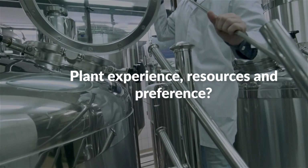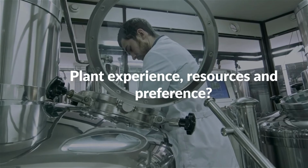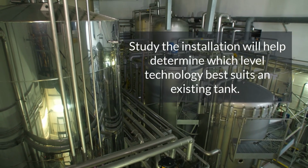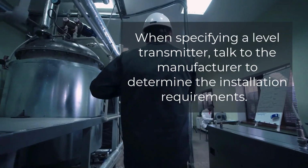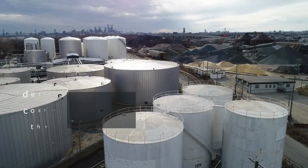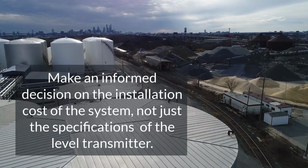Weigh in the plant's ability and inclination to support and service the instrument. No installation will be successful without it. Studying these areas of the installation will help determine which level technology best suits an existing tank. When specifying a level transmitter, talk to the manufacturer to determine the installation requirements on each tank and make an informed decision on the installed costs of the system, not just the specifications of the level transmitter.